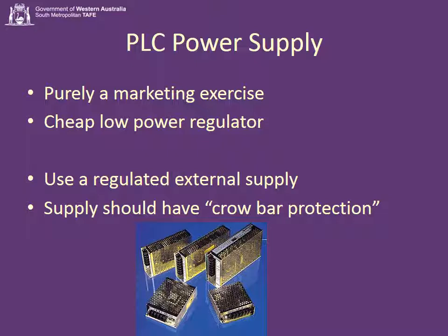Now, I better talk about power supplies while we're here. Typically, PLCs, especially the ones on BMS systems, come with 24 volts available on them. Now, don't use that 24 volts to try and control your valves. What will happen is you'll just burn out the little voltage regulator within the PLC. So you need to have a good external power supply. It needs to be a regulated external power supply which gives a lovely DC value, 24 volts.